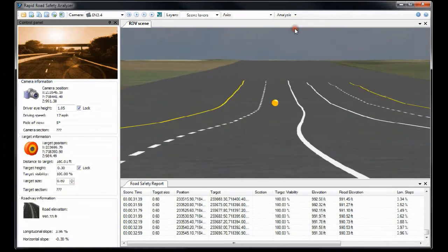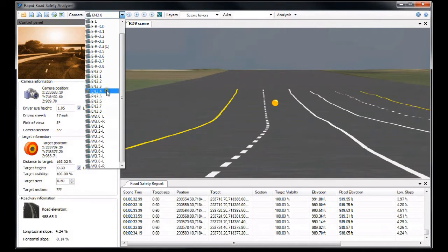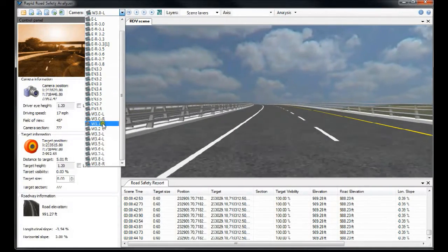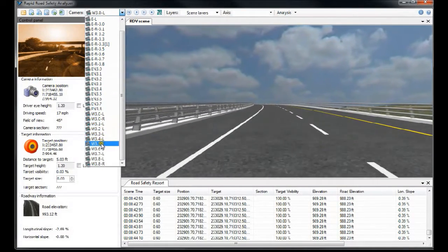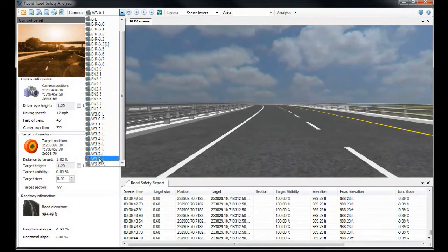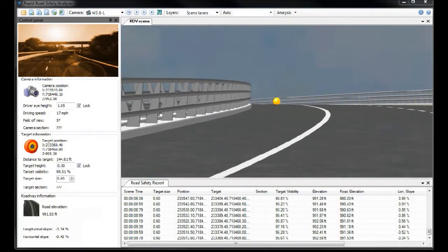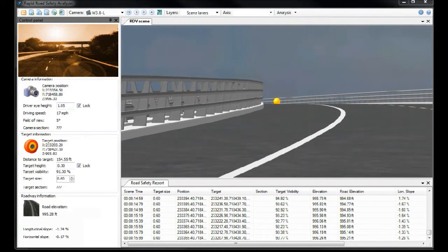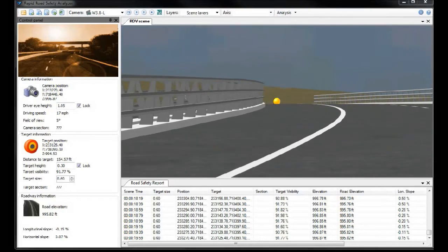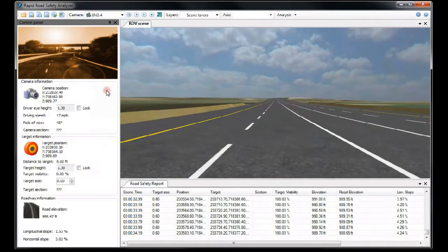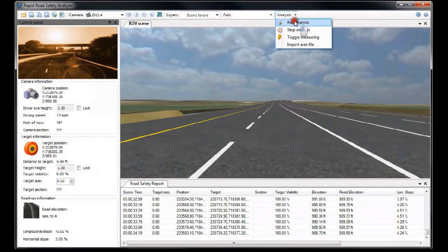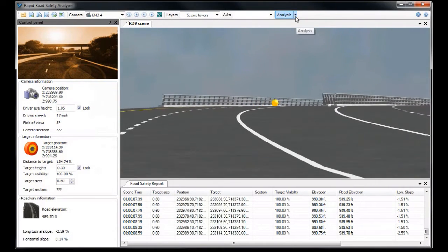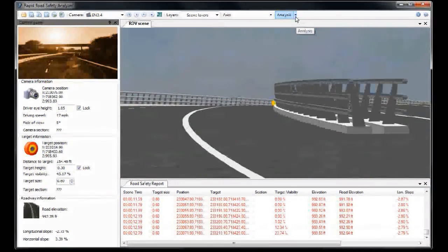After these 2 initial simulation runs, we set up additional paths for our simulation at 10 centimeter increments to find the optimal solution. Notice that as the vertical slopes change along the alignment, updated values for site distance are calculated and evaluated automatically. Within a few minutes, all paths and configurations were analyzed, resulting in a recommendation to the DOT of a 3.4 meter shoulder, which optimizes cost savings while ensuring that the safety of the design is not compromised.